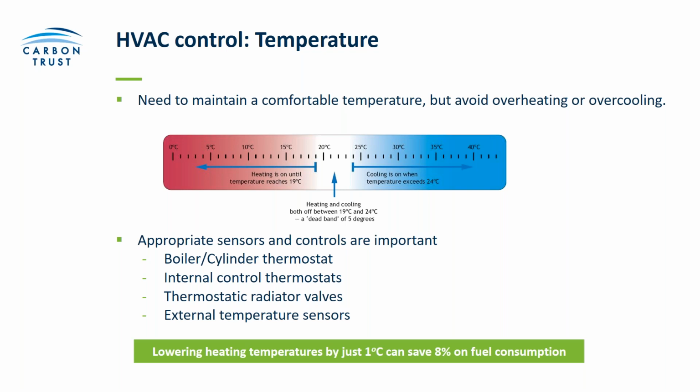But the cooling systems in particular, I think are worth looking at to make sure that you're not overcooling, and that would apply in particular in the likes of server rooms, where temperature set points can be set much lower than required. And in those cases where there isn't the same level of occupancy, you can get away with higher temperatures. Certainly around 24 degrees C would be possible, and that'll just reduce the need for cooling on your systems.